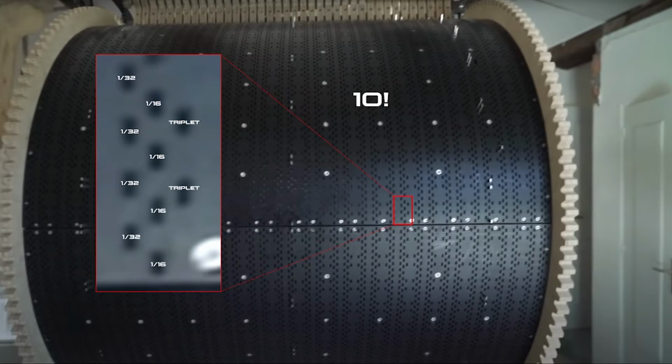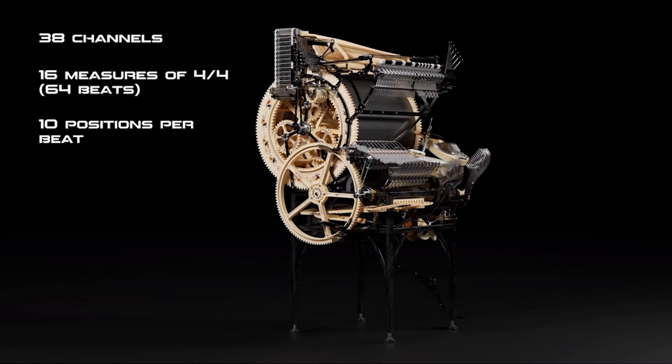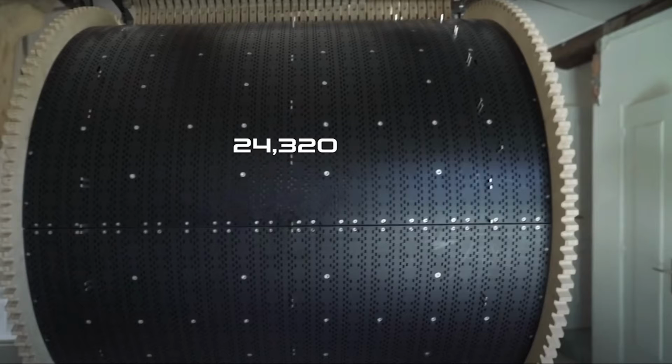So what we know is we have 38 channels that play 64 beats apiece, and of those 64 beats, there are 10 positions per beat. That gives us the math 38 times 64 times 10 equals 24,320 holes in the programming wheel.